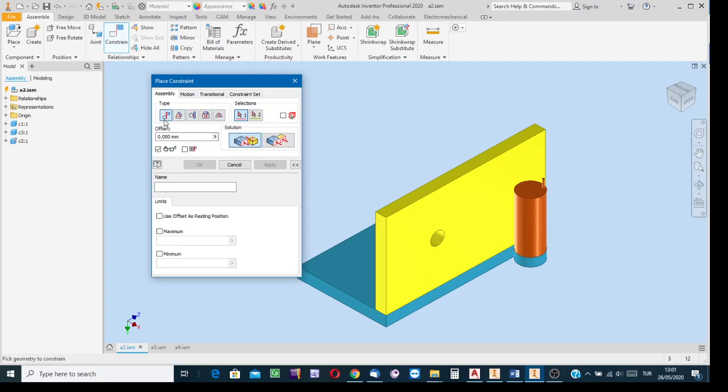Here, what is complementary? Well, today I'm going to talk about, as one of the complementary things, motion type constraints. If in the assembly there is a mechanism, where one component is to move in a linear direction or about an axis, rotary type motion, then to be able to make a simulation, to say that this is a movable part and while it is moving the other one is also actuated by that component, use this type of constraint. Motion type constraint.